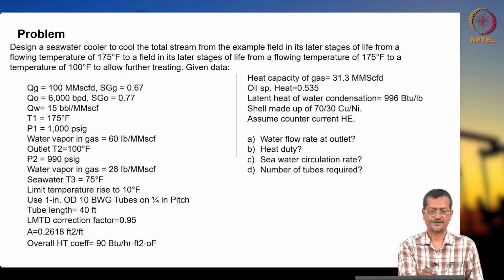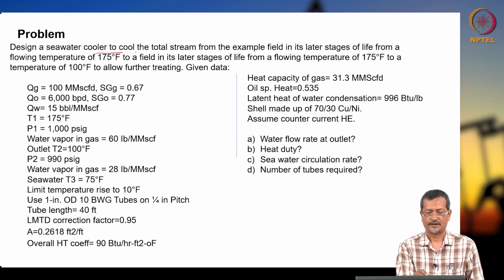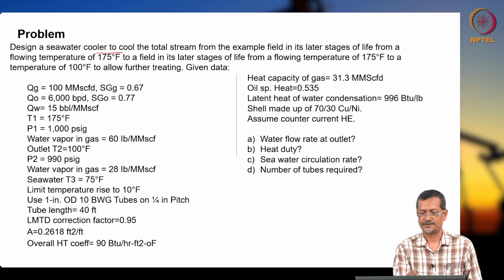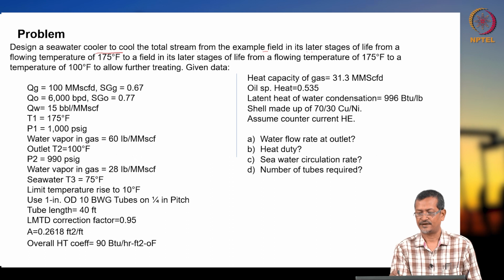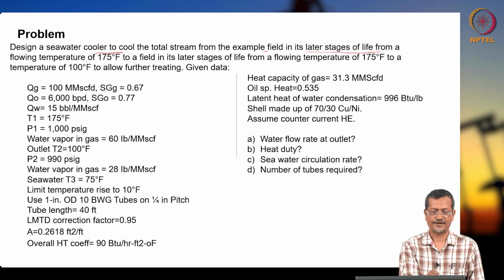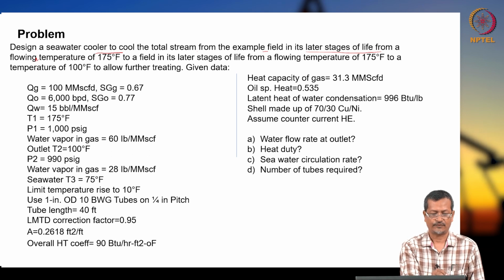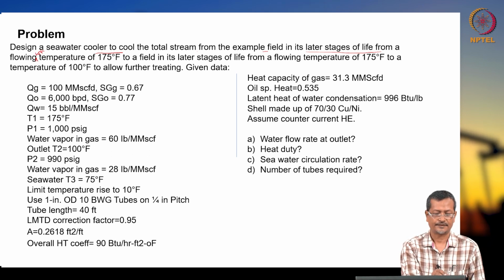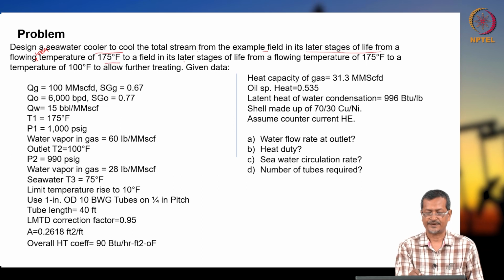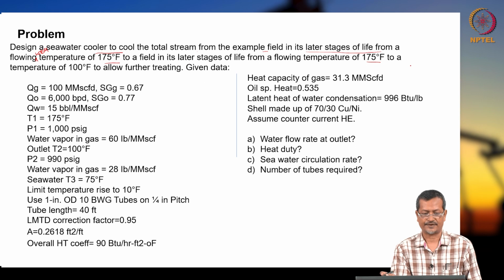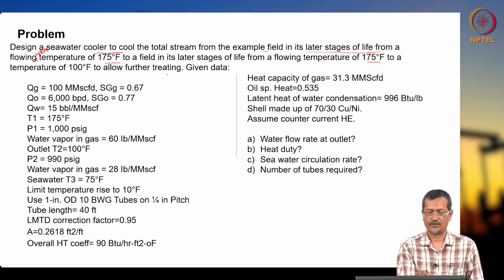So here is one seawater cooler. Seawater means offshore application, cooling system. Total stream, not steam, stream from the example field in its later stage of life, a flowing well. Flowing temperature 175 degrees Fahrenheit, to a temperature of 100 degrees Fahrenheit to allow for the treating.